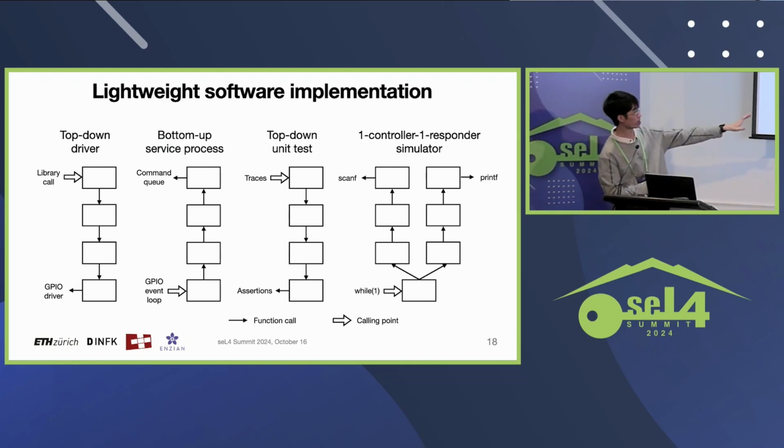And by the way, on the right, we also show that we can actually generate a simulator for the whole I2C network in this way. So we have an infinite loop that calls into both the controller stack and the responder stack, and they are connected to scanf and printf, and there we get a simulator.